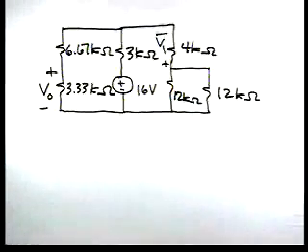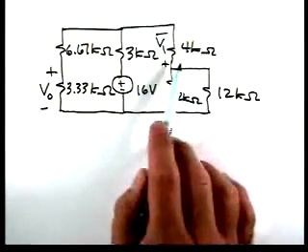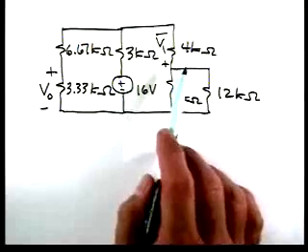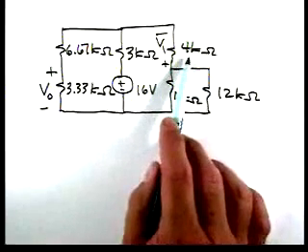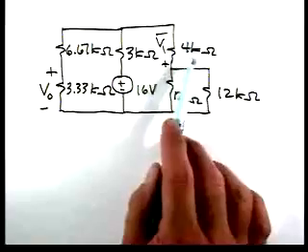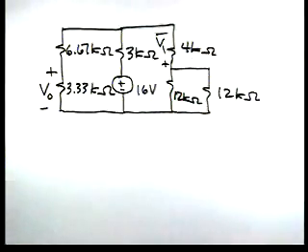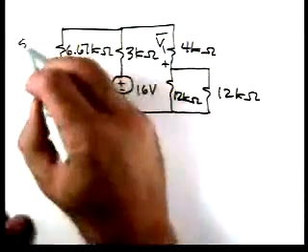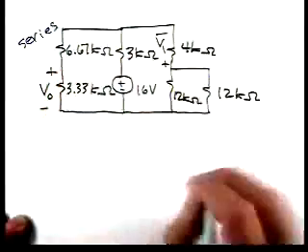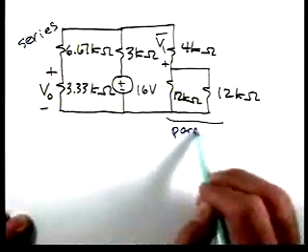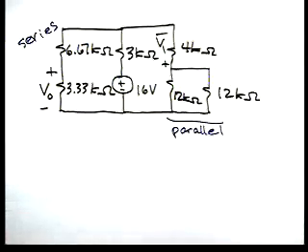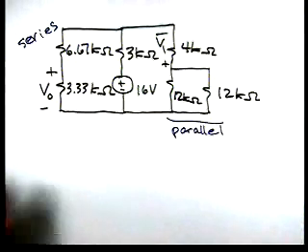And if we look at our circuit, V0 is still on there because that was a voltage across the parallel combination of the 5K and 10K. V1 is still on the diagram because we didn't combine the 4 kiloohm resistor in any combination. Now, these two resistors are in series. These two are in parallel. So let's further reduce the circuit then.